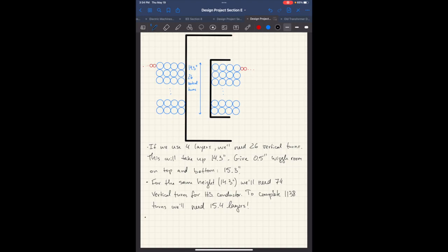Now, it's getting kind of thick, right? We need to make sure that the window is wide enough. We want to design the window so that this will only take up 75% of the window. So we care mainly about this length, which is from all these conductors and then all the 15 conductors. So we can calculate the width. We don't care about outside the window. In other words, we don't care about these guys. We only care about this width.